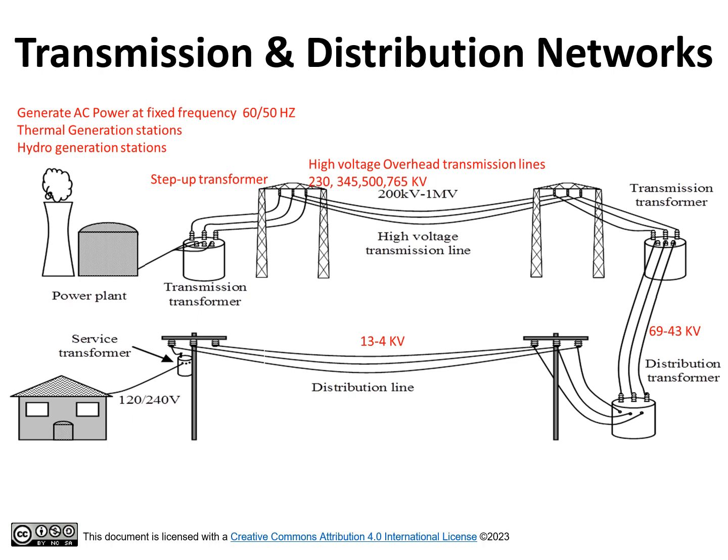Most of the transmission lines are overhead transmission lines. The reason for using overhead transmission lines instead of underground cables are the cost and ease of maintenance and repair. The cost of underground cable installation and insulation is huge in addition to the high cost of repair and maintenance.